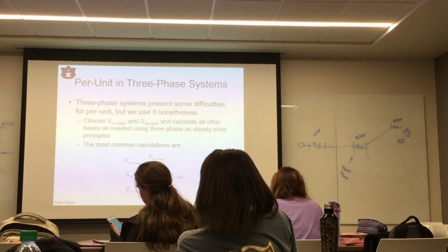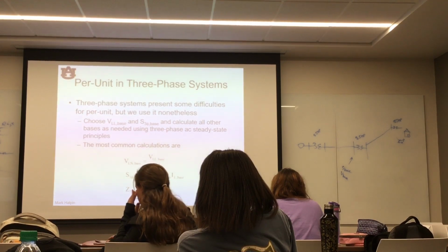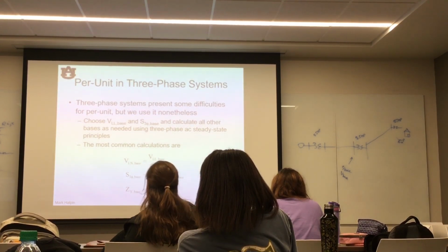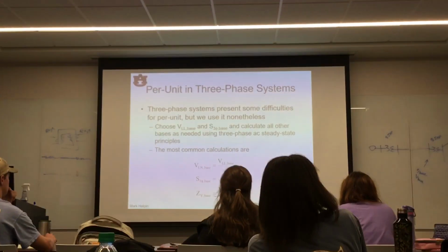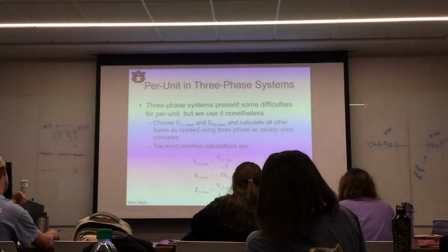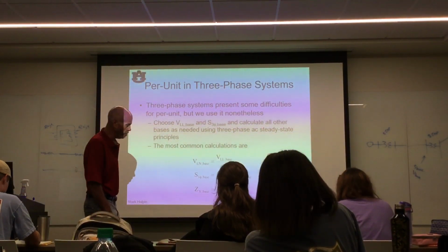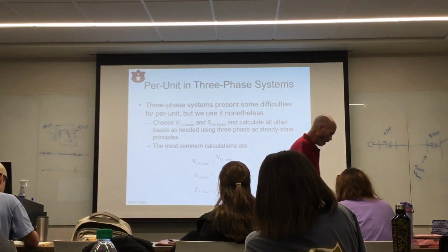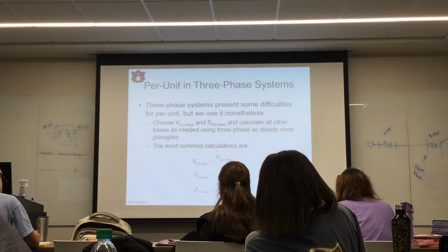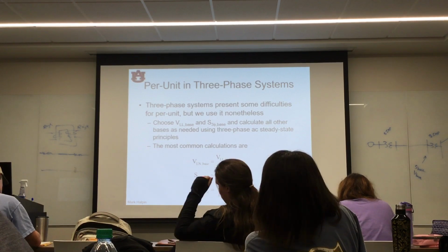What about voltage? Well, in three-phase applications, I've got line-to-line voltages, and I've got line-to-neutral voltages. Which one do you want to pick? You could pick either one. Customarily, we pick the line-to-line voltage. So, in three-phase applications, our two picks are line-to-line voltage and three-phase apparent power. Okay? Everybody does that. And nobody says that. In the event that you deviate from that well-entrenched practice, it is your responsibility to draw attention to the fact that you deviate.